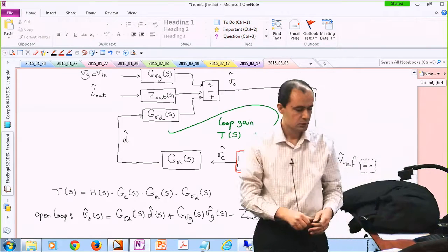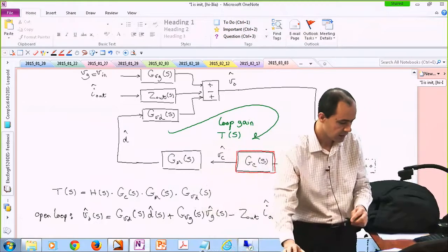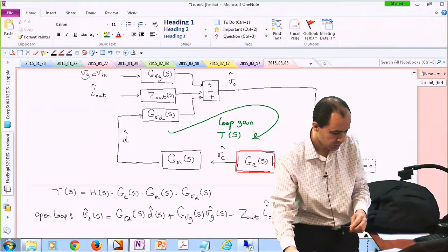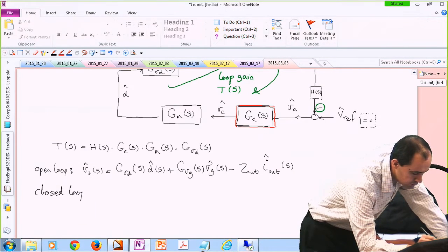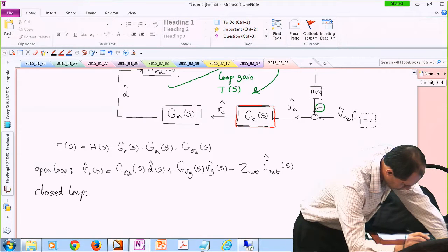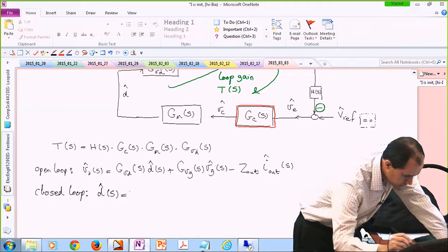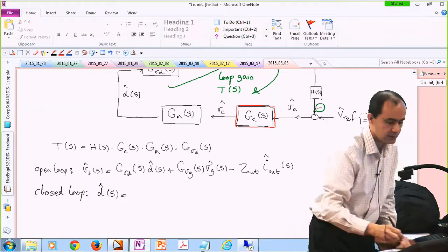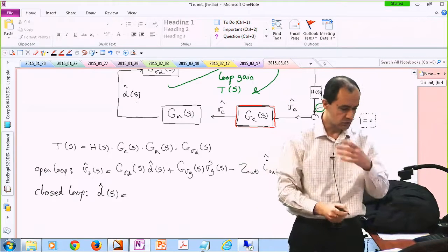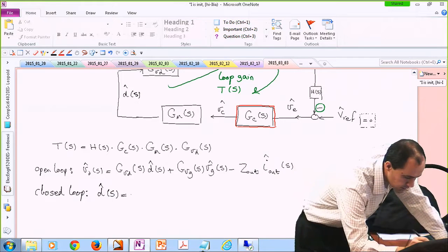All right. So this is a very general equation relating the inputs and outputs of my power converter. However, now because we have closed the loop, I can describe the duty cycle in this form. The duty cycle that is applied to the converter is related to the output voltage of the converter. So I just have to write that relationship.